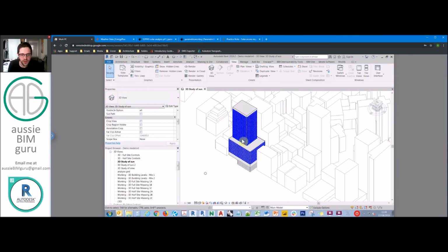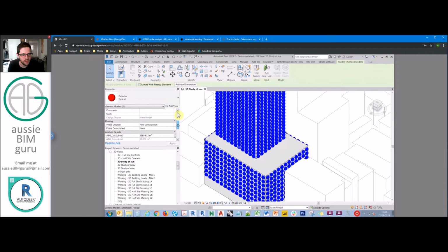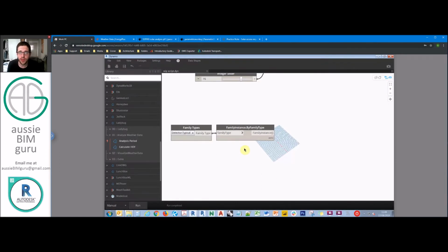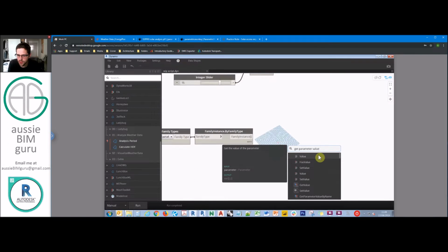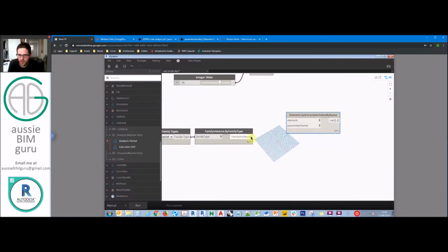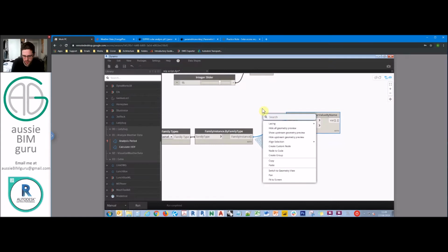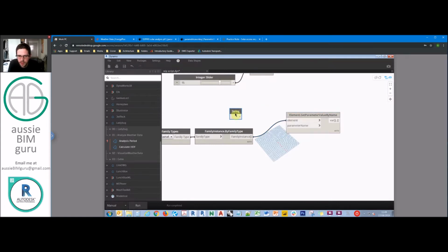So we need to filter them out, and the way we're going to do that is to use some filters. So first we're going to just obtain all the sensors that belong to option 1B in this parameter, and then we're going to find all the sensors that contain the word tower in comment 2. And that way we won't get any of our podium sensors. The reason we want to do that is the more you can refine your study, the faster it will go, because we're going to be checking a lot of things, so it's going to be a slow script to run. So we're going to get some parameter values of these sensors in order to filter them down. So we're going to get the parameter value first of the parameter for comment 1. In my case, I've called that ABG data comment 1.